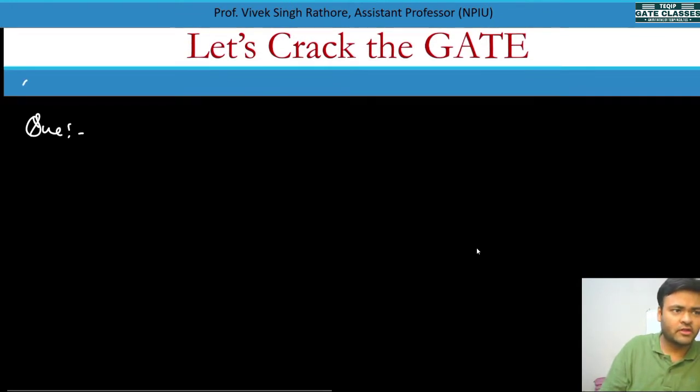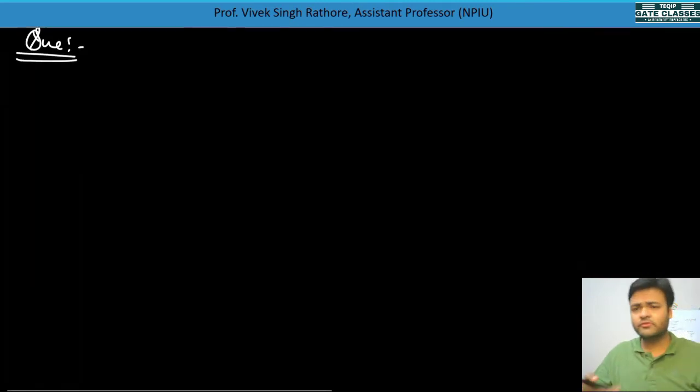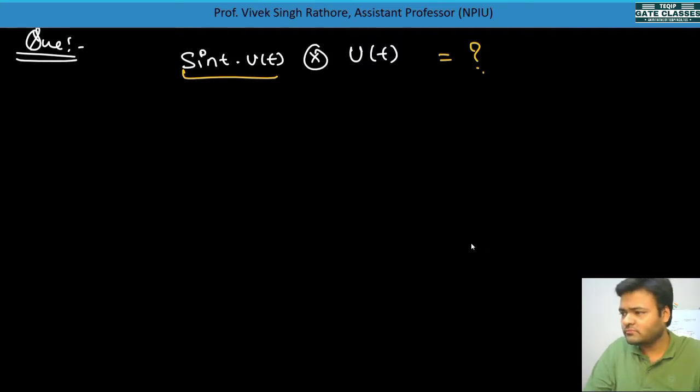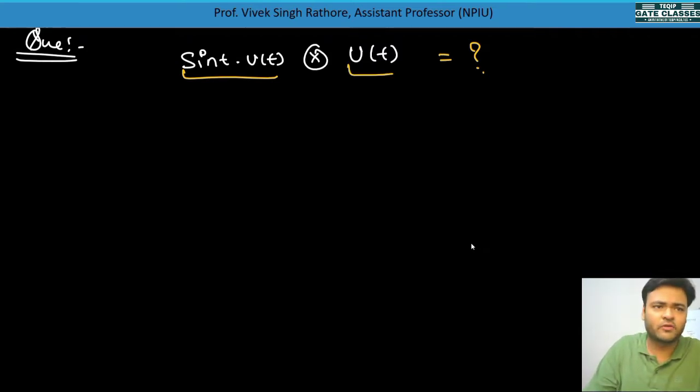We'll write some questions which we have not discussed in the last class. Like, if you have been asked to perform convolution between sin t into u(t), convolved with, let's suppose, u(t) only. You have been asked to convolve these two signals and get the output response. So this is your input, and let's suppose this is your impulse response.